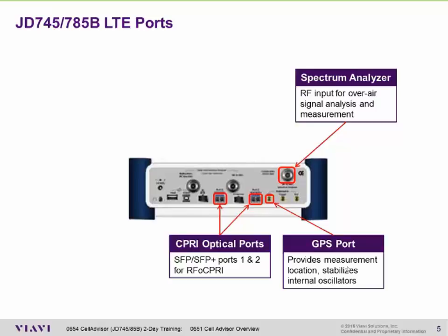But more importantly, the more you use that GPS antenna with the instrument, it actually serves to automatically calibrate the OCXO, the oven controlled crystal oscillator. This means that frequency error problems can be clearly seen when you have an atomic clock as your reference. And the more you use that GPS antenna with this instrument, the better it will remain calibrated to match GPS timing, which is the most accurate timing source that you can otherwise have. So again, I make it a habit every time I set up the instrument to use a GPS port.